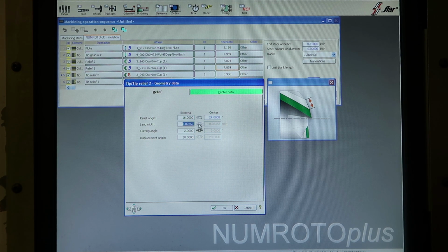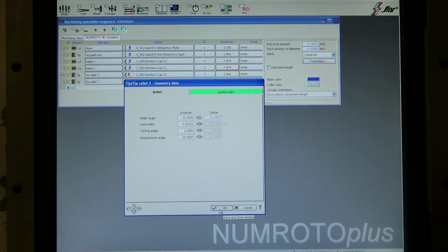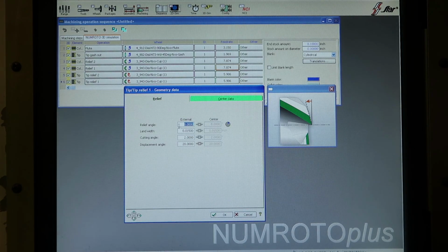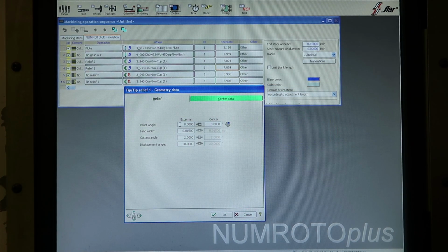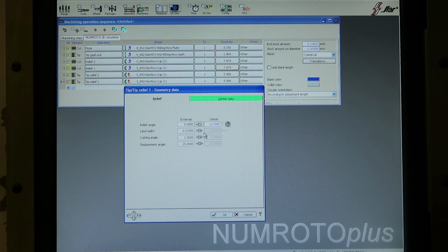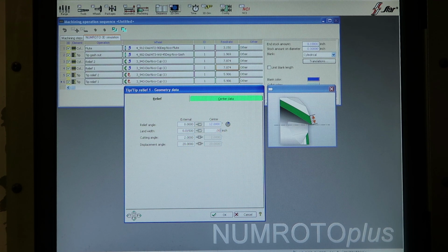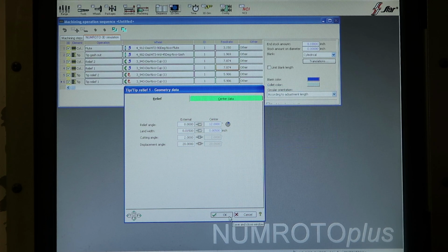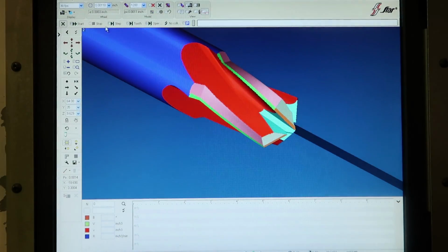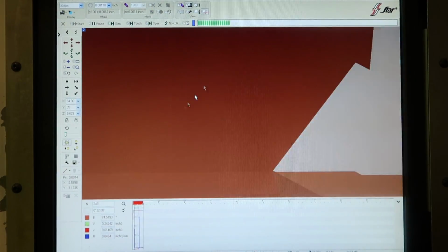The land width doesn't matter. This is secondary clearance. It's going to just take care of itself because of the primary clearance on the tip. But we're going to also vary this to a little steeper angle right at the tip. And we're going to taper this land down to say 5/1000ths of an inch right at the tip of the tool. So let's see what all that looks like before we get going here too far. Oh, can't see it there.